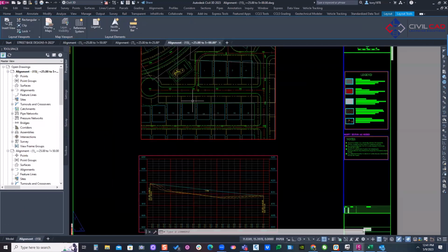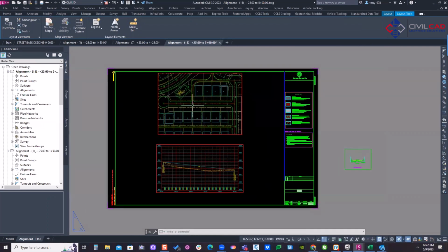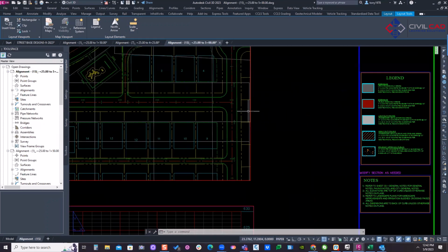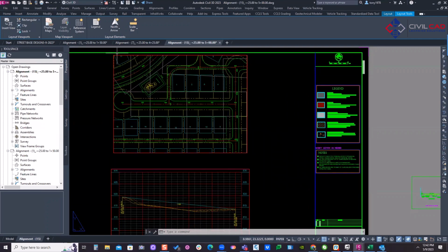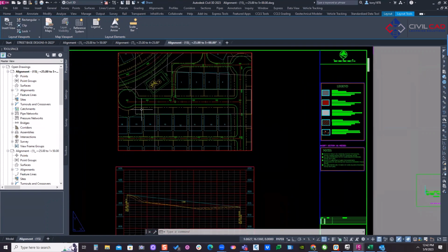There's only labels just for the plan view also. That's it. Nice, clean drawing. Now it doesn't have to do all this data referencing and linking. I'll just hit the update button now for the XREF, and I'm good to go. And you'll be using your match line. I'm just using this very generic match line, but you'll be using your match lines in your template.